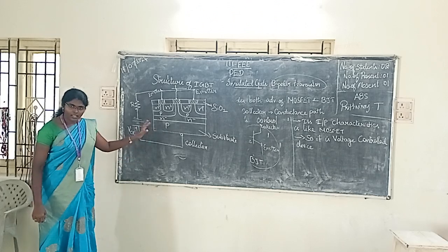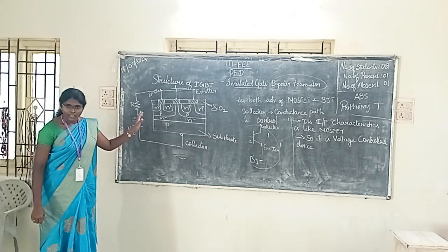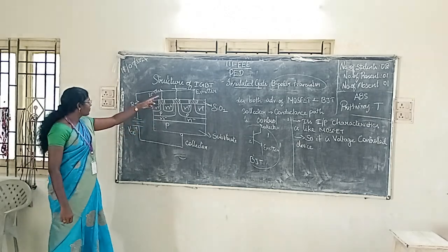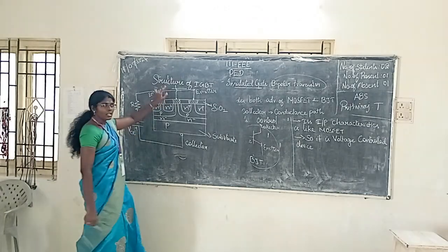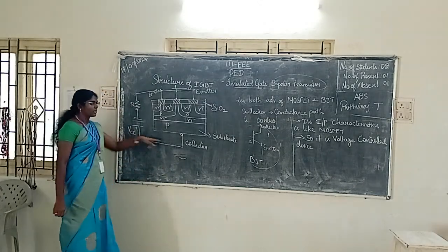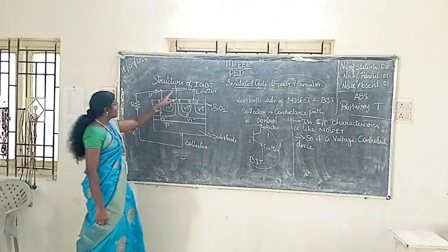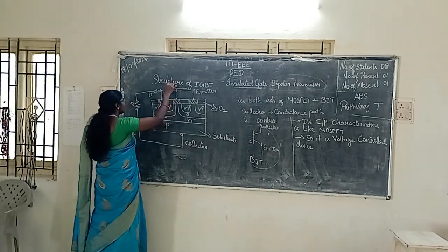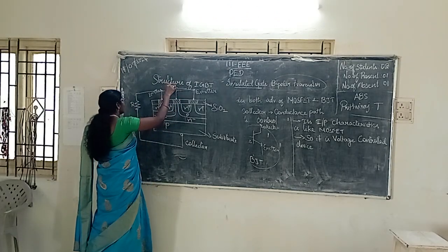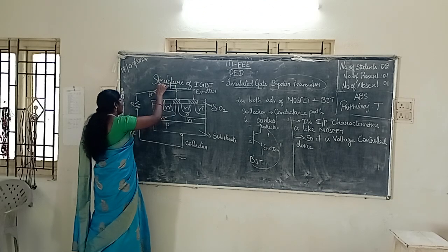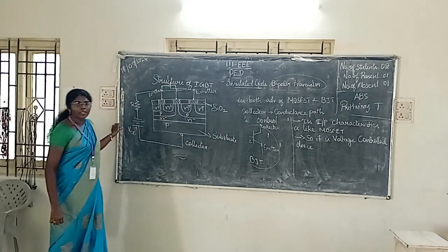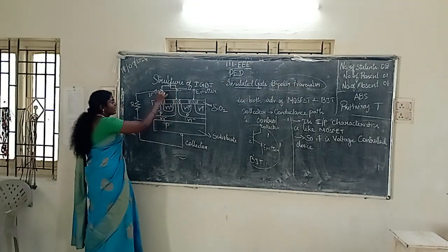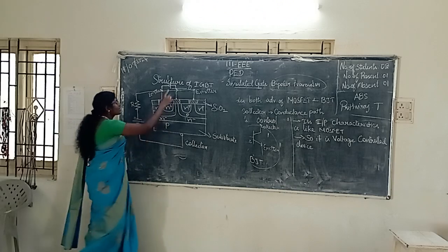By using voltage, that is across the gate. In the MOSFET it is VGS, and here it is going to be VGE, gate to emitter. It should be connected to the emitter. If you notice, here I am not connecting, here it is connected. So what is this voltage called?